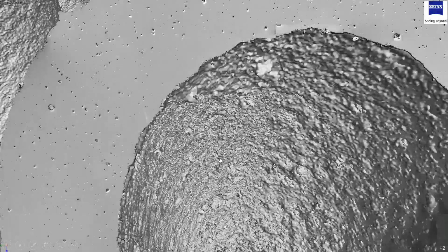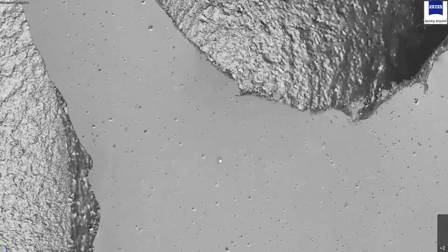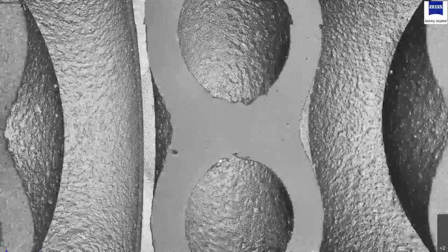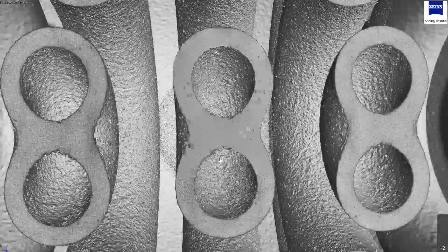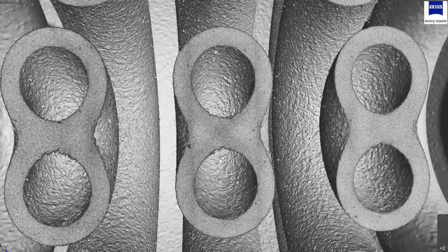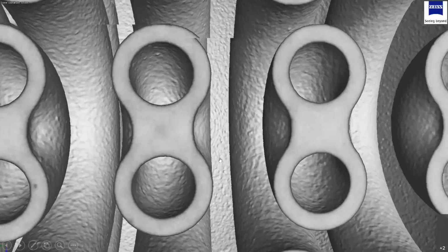On the other hand, if you go with optical microscopy or SEM directly, where we are able to see only the finest of the pores, you are limited to collecting data from a very small region, and that region may not be representative. So by combining all these different approaches, you're able to see the entire part, identify the regions which are representative but not captured by the coarser resolution, and then use a higher resolution instrument to go in a pointed direction.